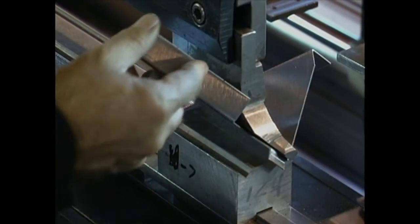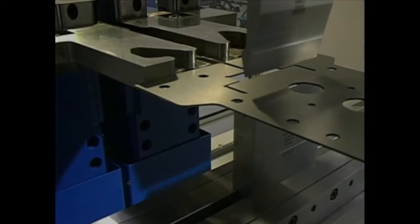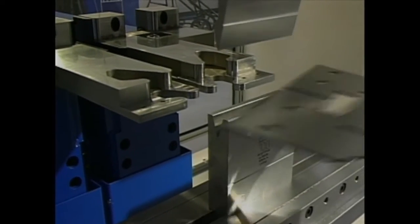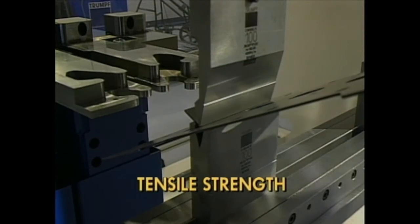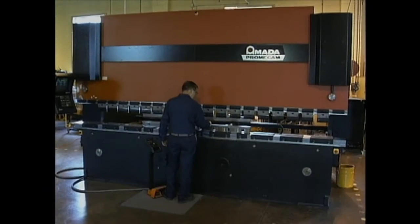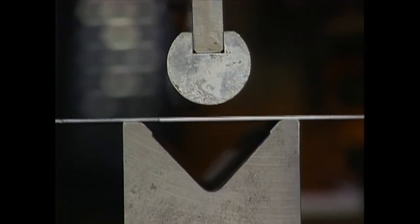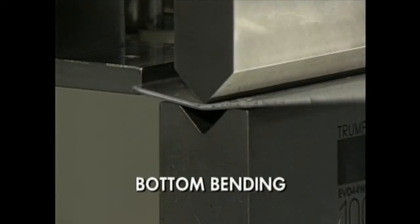Bending is the creation of three-dimensional shapes out of two-dimensional material. Bending is a method of producing shapes by deforming the metal beyond its yield point, but not past its ultimate tensile strength. The press brake is the most common kind of bending machine. There are two major categories of bending: air bending and bottom bending.